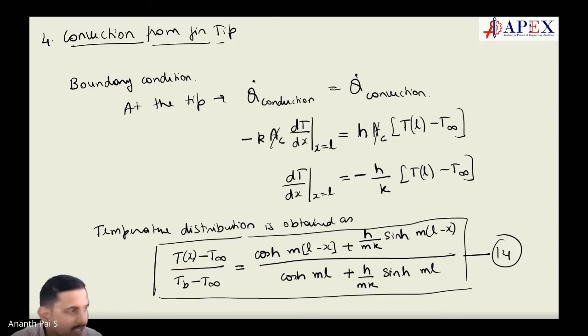Are there other cases which can happen here? Heat transfer in this case is, see, at the tip. It is not very long. It is not insulated. See, first case is what? Very long. What's the second case? Second case: not very long, but I've insulated the tip.